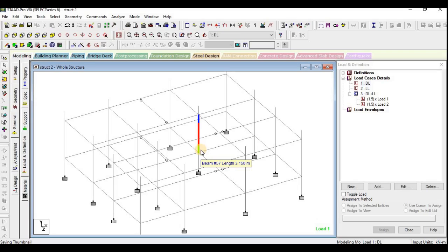Instead, you can model the slab in a separate portion and check the shear values and moment in the structure, that is, the bending stresses, as a plate analysis. If you design as a plate analysis, you cannot find the reinforcement details in that section, because we are going to analyze using finite element analysis.